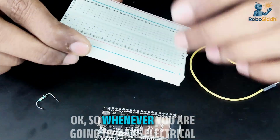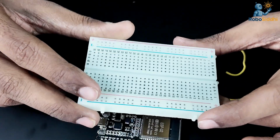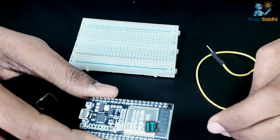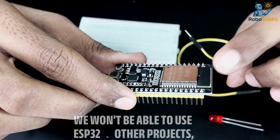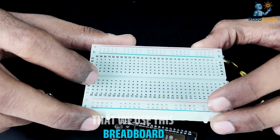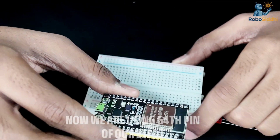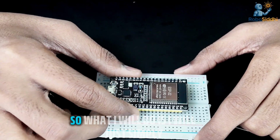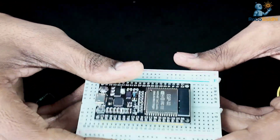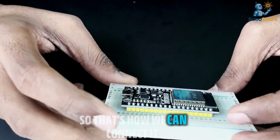Whenever you make electrical connections using soldering, the connection will be permanent. Now if we blink an LED with the ESP32 and solder it, we won't be able to use the ESP32 in other projects, right? So to avoid that, we use this breadboard. We are using the G4 pin of our ESP32. So I will simply plug it into the breadboard like this. Now the breadboard is fixed and we can use all of its pins, right? So that's how we can connect it.